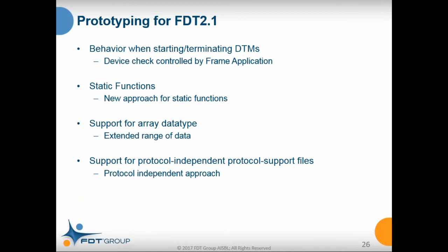With FDT 2.1, we defined the ability for the frame application to control the execution of the device type check. We want to test that, because when the device is not accessed online, the OPC server shuts down the DTM and loads it again when an online value is requested.